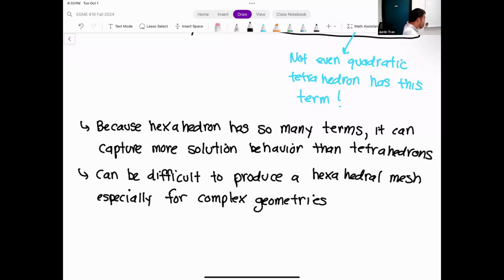In fact, we're not going to discuss this particular element type here, just because it's not a setting within ANSYS, but there's an element type that's in between a hexahedron and a tetrahedron, and that's called a prism element, right? Some of you have picked up on this already. A lot of times if you try to make a hexahedral mesh, ANSYS will give you a warning message that a certain percentage of these are prisms, okay?